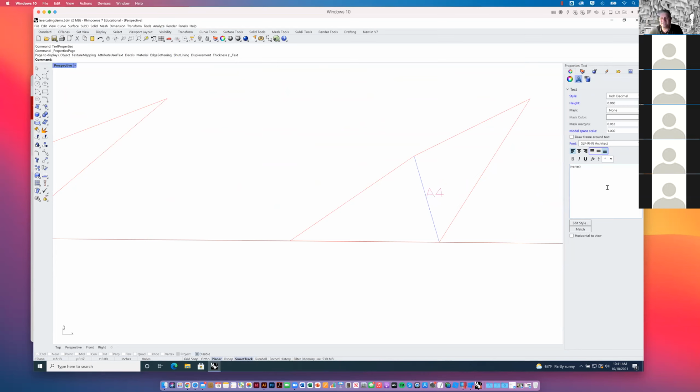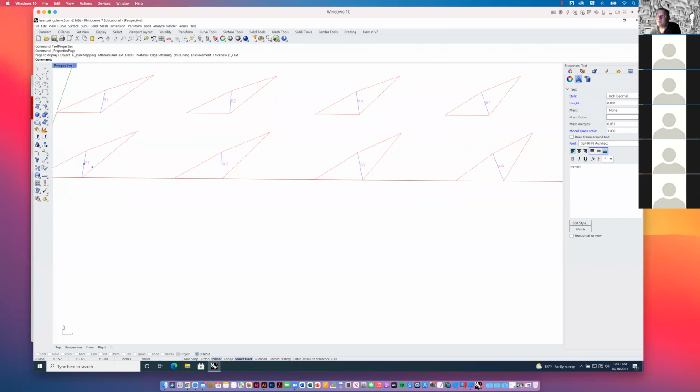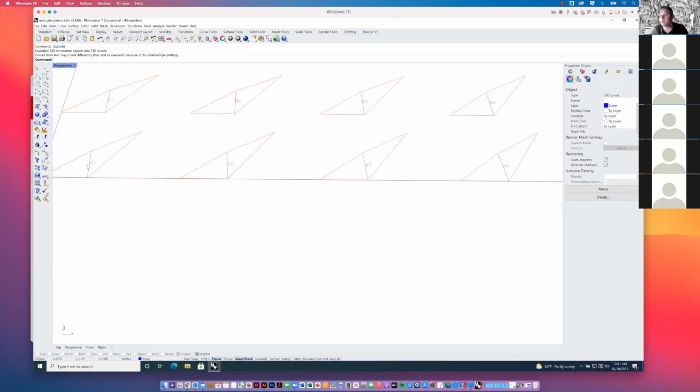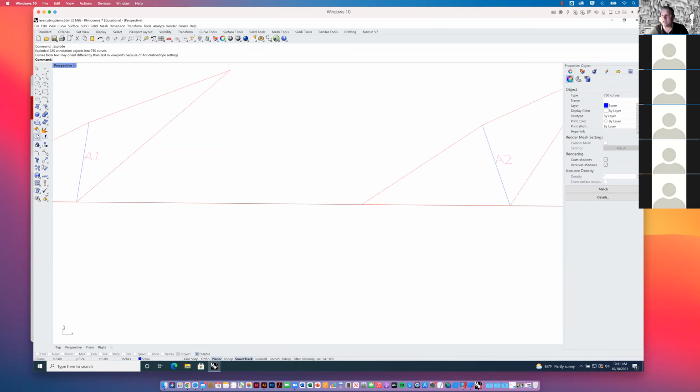Of course, the sound effects are always optional. Anyway, let's see. All right. So I've changed the properties just once. I went to cell text, SEL, TEXT, short for select text. Then I typed in text properties, and it let me change all of these all at once here in the properties. All right. Let me just select text one more time. What happens if I explode it? Will it just become curves? Oh, yeah. They become curves. All right. So now they're curves. And now if I hit join,